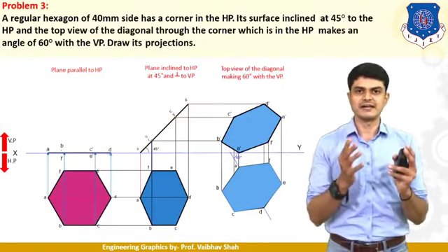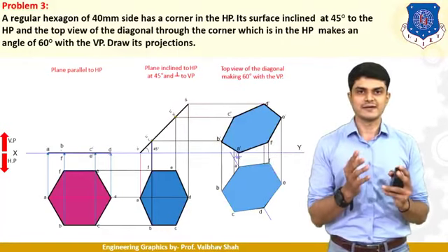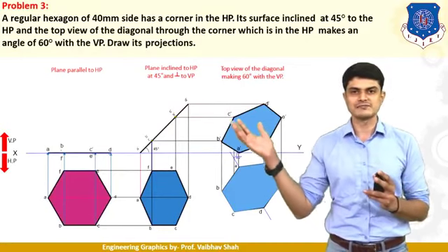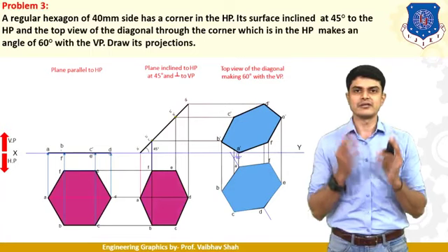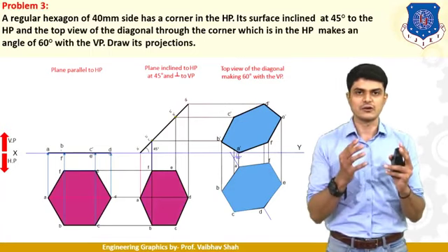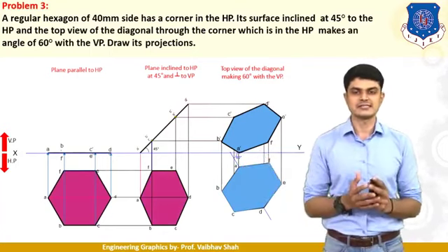As you can see, you should incline that horizontal line to the XY line at 45 degree. You should transfer each and every point of that line onto this inclined line with the help of a rounder. After transferring each point, draw vertical lines and horizontal lines from each point of your hexagon in order to find the top view of the hexagon in the second stage. So you will have ABCDEF here, the second stage hexagon.